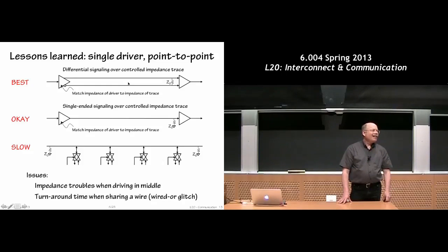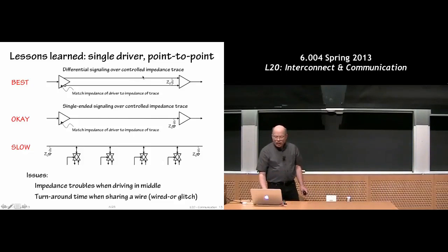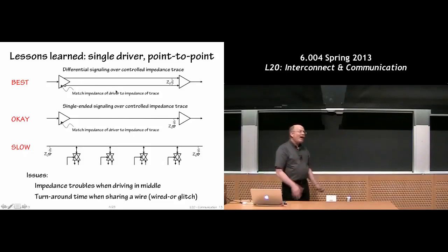Yeah? Any radio noise or electromagnetic noise will happen to both wires? Right, so the advantage of this so-called differential signaling is that you get very good common mode rejection. Something that would affect a single wire will in fact affect both wires pretty much the same. And in fact, you tend to engineer this so that anything that's happening happens to both wires.